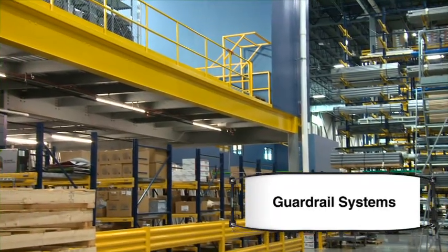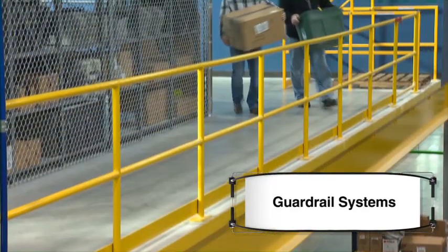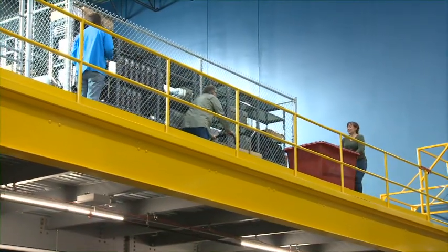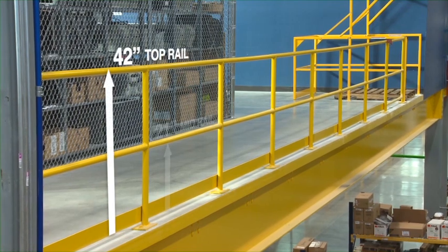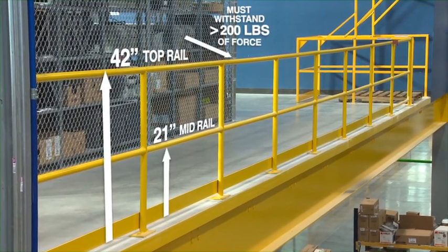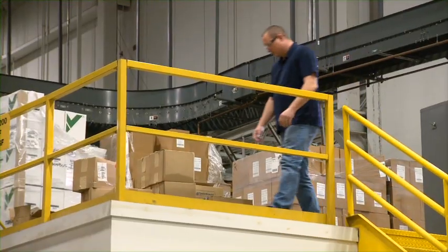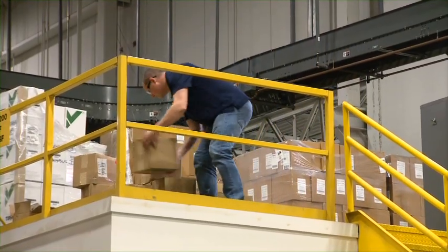Guardrail systems are a physical barrier used along an unprotected or exposed side, edge, or other area of a walking working surface to prevent workers from falling to a lower level. Guardrails are required to have a top rail and a mid rail. The top rail must be able to withstand 200 pounds of outward or downward force. In other words, they must be of sturdy construction and able to support a person of average weight in the event they fall against the guardrail.